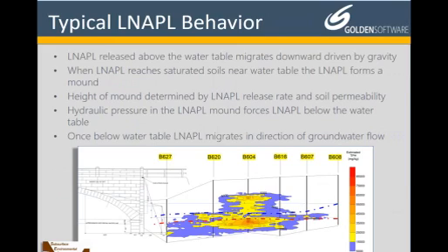This is a site that I worked on in my home state of Massachusetts. In this case, this was a number 6 oil site, and number 6 oil is a residual fuel that's left after refining out the lighter components of crude oil. Generally, it is heated up in order for it to flow through piping into plant boilers, for example.